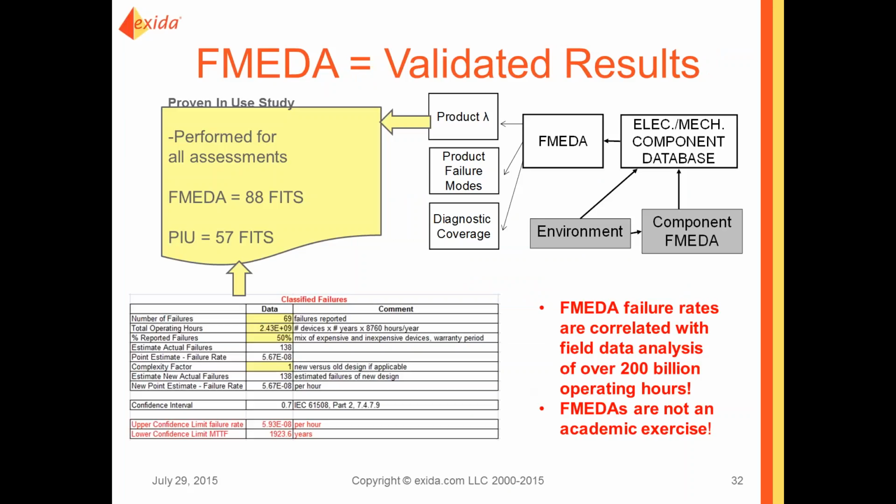One thing that we often hear is that an FMEDA, which is a technique laid out in 61508, is a predictive model. You build it up from a component database and you model a device, and sometimes people call that an academic exercise. Well, I think that's pretty far from reality. Every time we do an assessment, we do a field failure study of that device and compare it to an FMEDA. So here's an actual example of a solenoid.